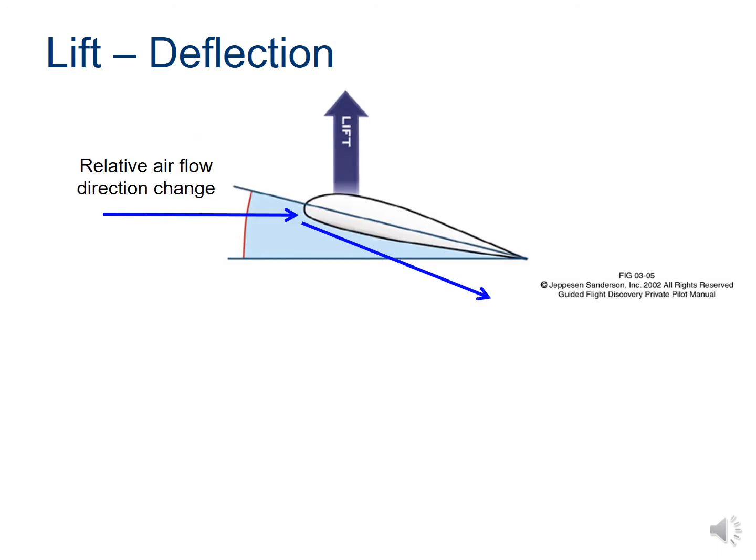The first source of lift we will consider is deflection. Deflection occurs when air molecules bounce off the airfoil at an angle from the horizontal, complementary to the angle at which the airfoil is placed, meaning they add up to 90 degrees. The air molecules will bounce off and accelerate away from the airfoil with a certain force.